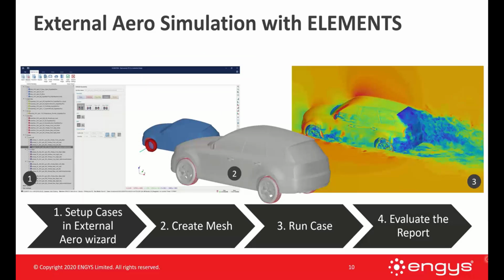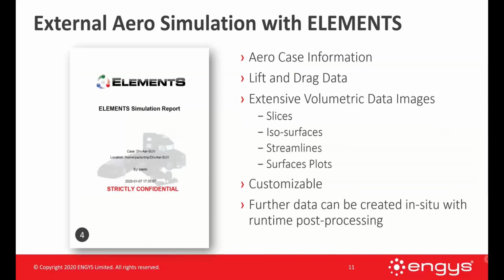Now, using the external aero interface, there are 4 main steps. The first being setting up a case for the external aero itself. Then there's creating a mesh, running a case, and then running and evaluating the report that's output. In terms of a report, it gives aero case information, lift and drag data, extensive volumetric data images, so slices, isosurfaces, streamlines, surface plots. This report is customizable, and we can obtain further data